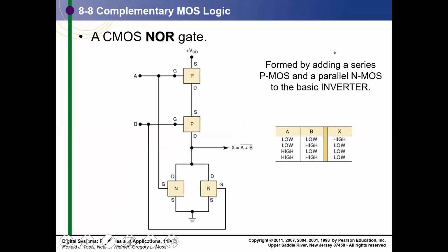And the NOR gate is complementary. The function is (A plus B) bar. First we draw the N network. A plus B means A is in parallel with B. So input A comes over here, and this is a transistor with input B. The two transistors are in parallel, with one end connected to output and another end connected to ground. And the dual of this is series, so the P transistors appear in series.